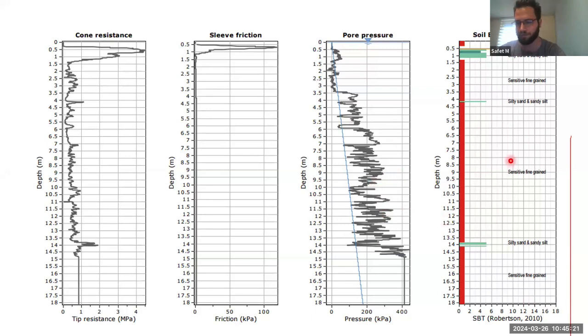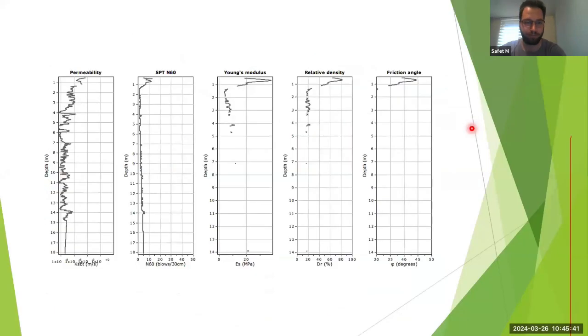So this is basically just the log of the CPT. Based on all those three parameters, you can get your log, and you can define what kind of soil you're going to encounter by excavating thereafter, and you can use it for design.